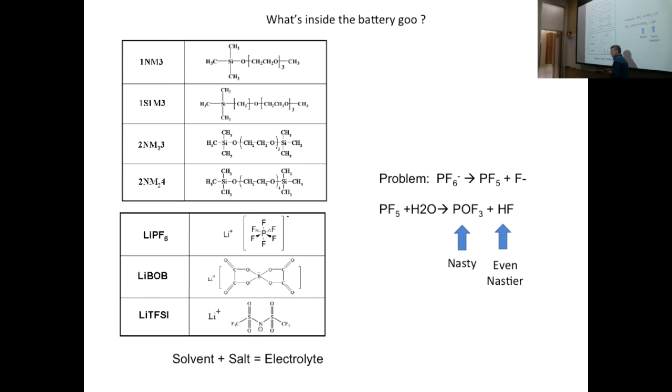And the challenge with the lithium-ion battery stability, as much as it's due to the electrolyte, so this is the solvent. Remember I said that an electrolyte consists of 2 parts, a solvent, which are these molecules, that's the liquid part, and then a salt. So we have a salt of lithium, so it's got a lithium cation, and then some kind of an anion: PF6, LiBOB, bisoxoborate, it's not named after me, and LiTFSI, trifluorosulfonamide, which is this compound here.